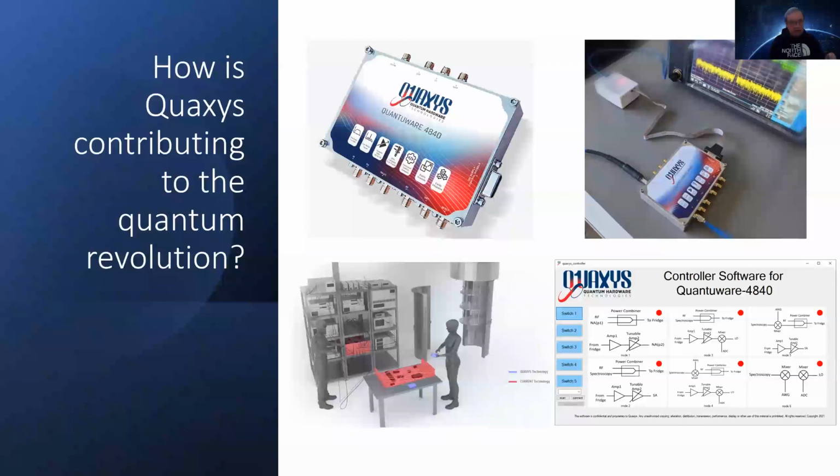As said before, you see different connections here for the fridge, where the output of the fridge comes into this box, and it gets amplified using low-noise amplifiers and goes to, for example, an IQ mixer for the down conversion. And it has outputs for the ADC, analog to digital converter. It will be down converted and goes to the analog to digital converter for the further processing.